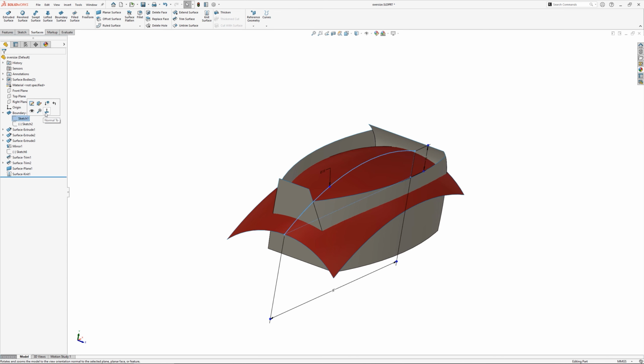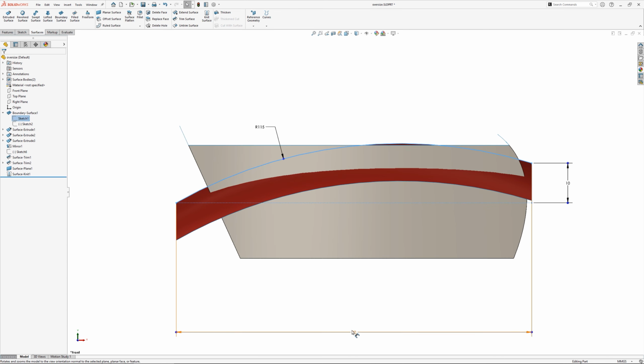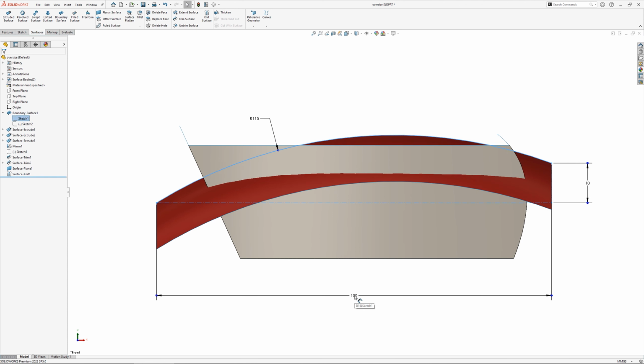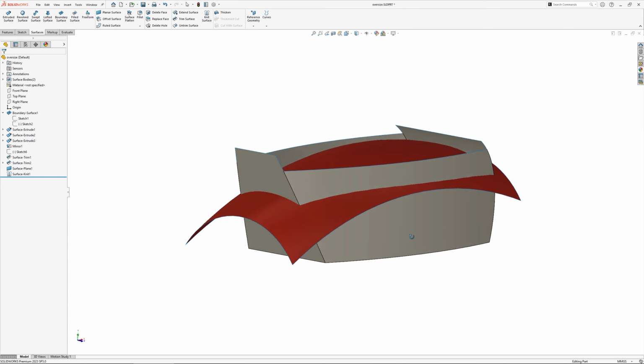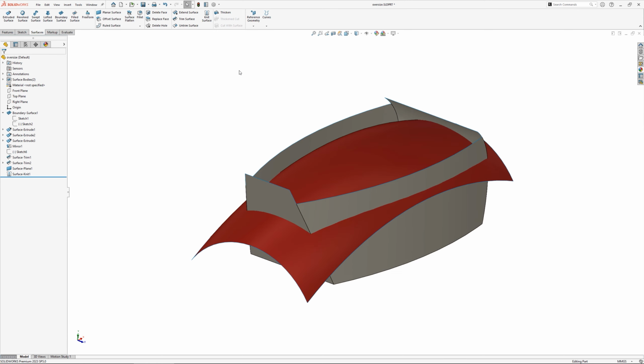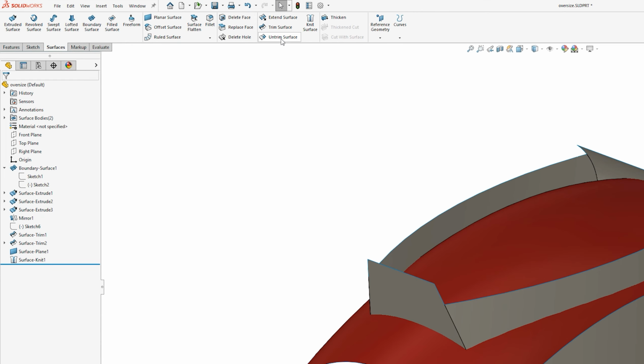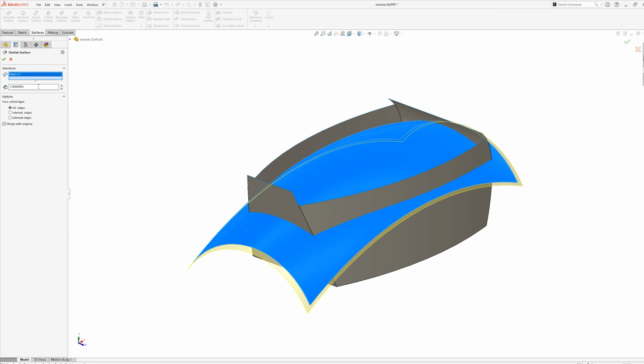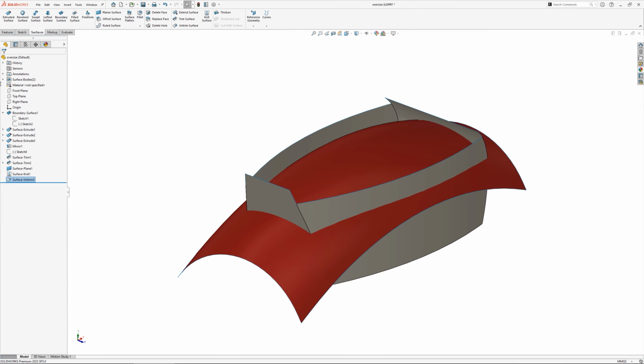Making surfaces larger than they need to be can be achieved in a few ways. If the surface is built from sketches, the sketches can simply be made larger and therefore the resultant surface will also be larger. Or, if the surface already exists, using the untrim or extend command will increase the surface size without any modifications to the defining sketches.